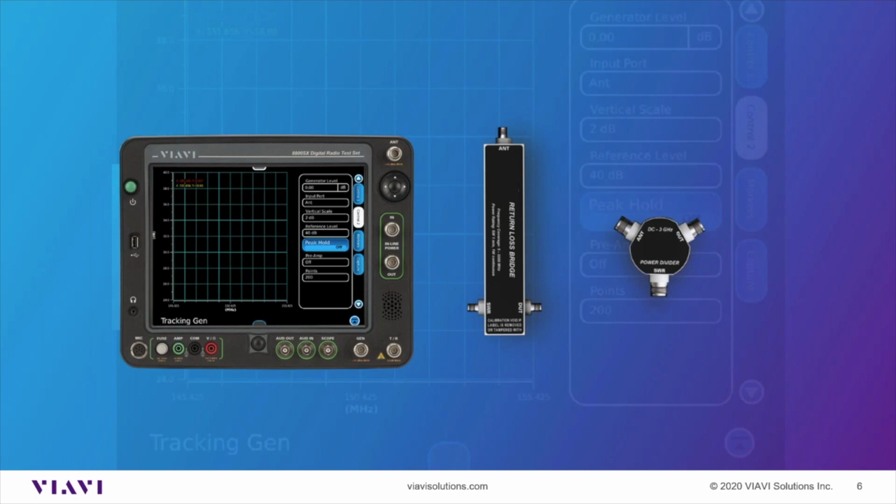The 8800 obviously has the VSWR scale as well as a dB or return loss scale, and the 3920 does not have that VSWR, but you can still measure your return loss. There are calculators and tables on the web that you can download, or apps on your phone, that will let you do a conversion if you know what that return loss is, and it's the same process.